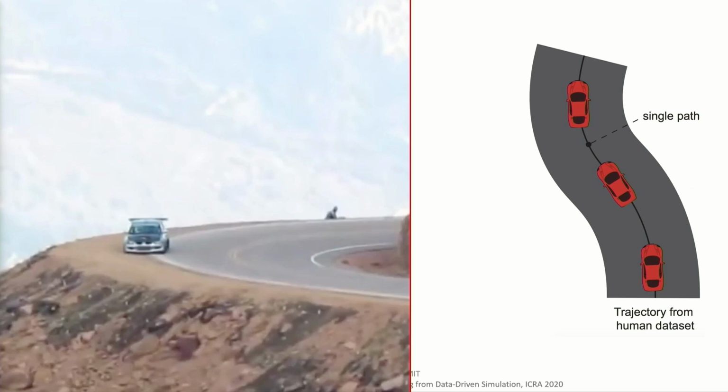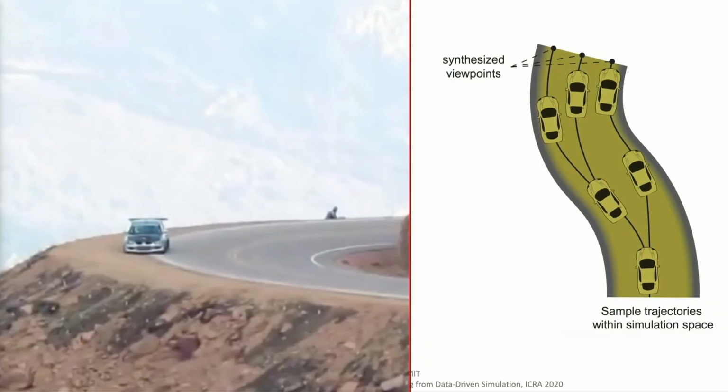Well, collecting data for near crashes or safety-critical scenarios is not feasible to do directly from the human drivers, but we can generate it in simulation. And the way we have solved this problem was by creating a simulation environment where we collect one data set from a real human who drove a real car. And then in simulation, we can turn that data set into anything we want. We can turn it into erratic driving. We can turn it into accident or near-accident situations. And so since this is done in simulation, it's okay. We don't have to destroy the vehicle.